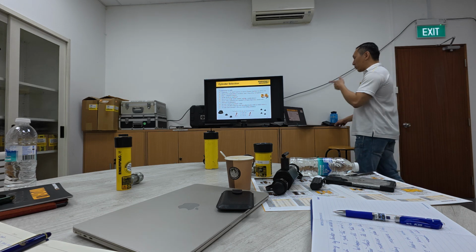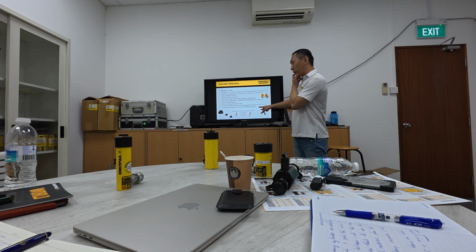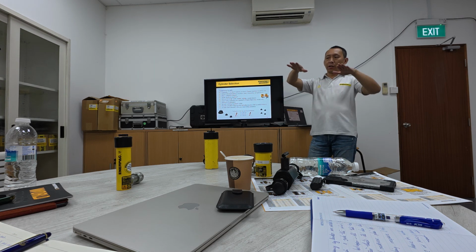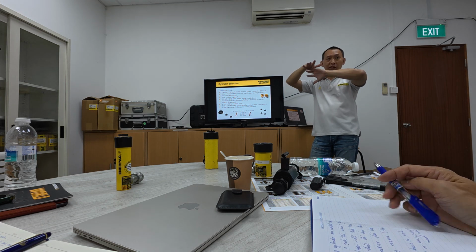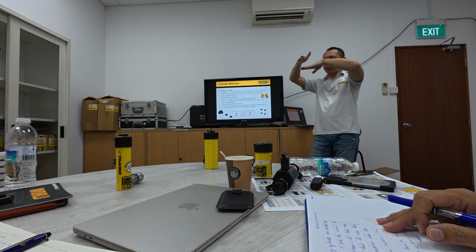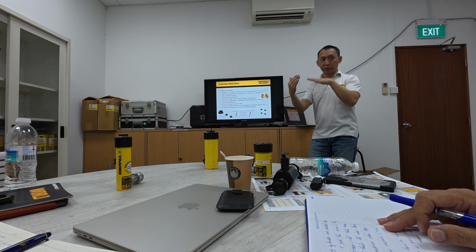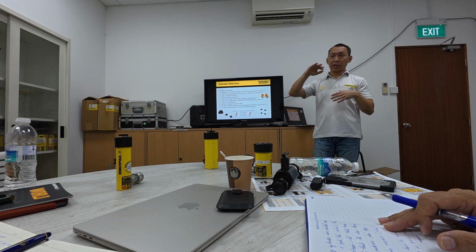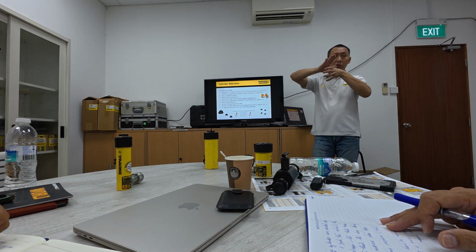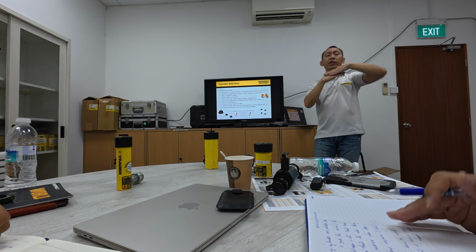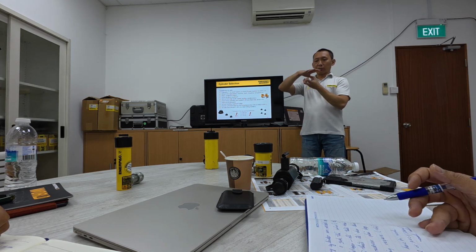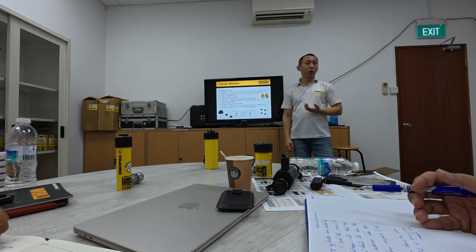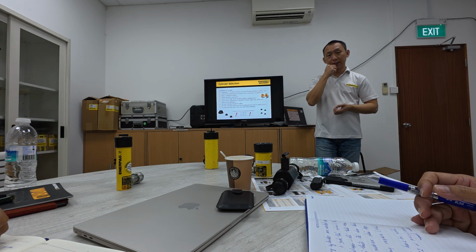So this is one to ask, especially for load lifting applications. Then of course, there's some side load because the contact surface is uneven. The ground might be uneven, so the contact surface might not be even. That's why you probably have to use a tilt saddle. You can go up to 3 to 5 degrees. It's like a ball, so you tilt accordingly. That will help to minimize the side load to the cylinder.